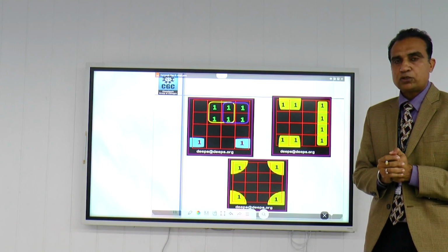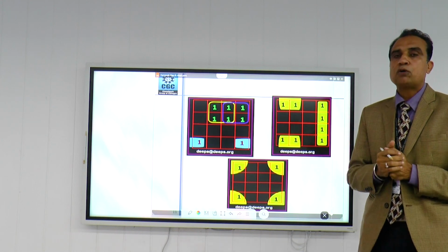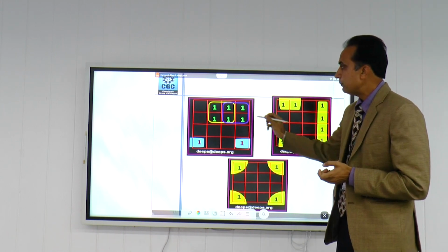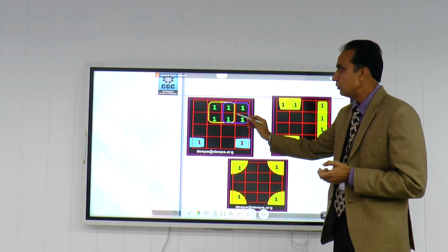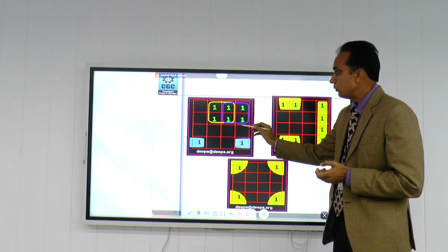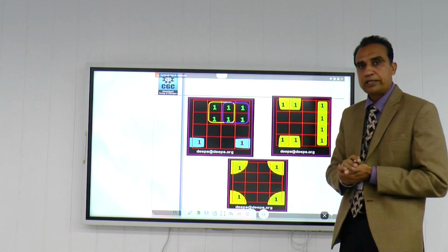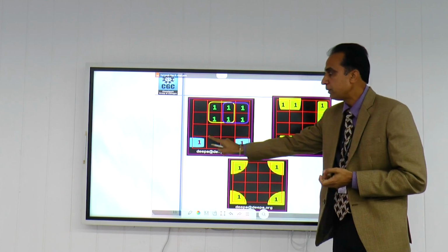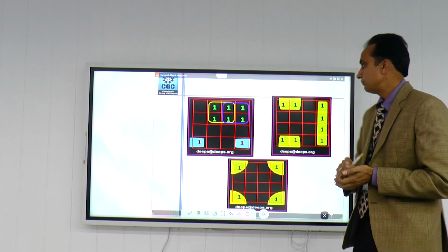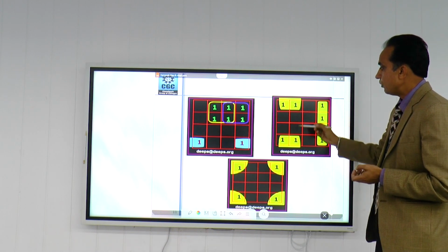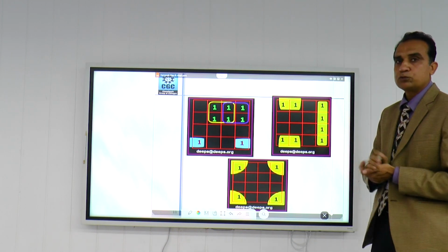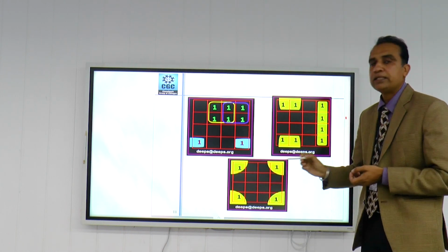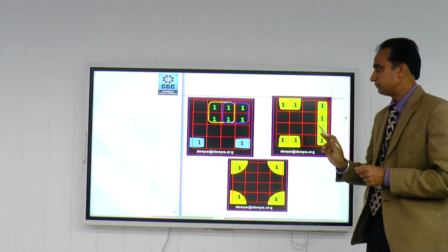These are the examples of how we put the values into the K map, then how we perform the grouping in the K map. Now in this example, we show the overlapping of the groups. This is a group of 4. Then again a blue color group is a group of 4. Groups can overlap. This is a folded part of the K map. Means this one can participate in a group with this one. Similarly, these two ones can form a group of 4 ones by including these 2 ones. This is again a group of 4. Similarly, corners can participate in a single group of 4 ones.